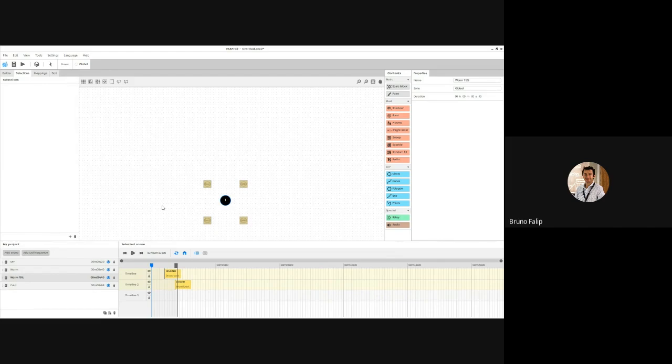Because, as you remember or not, when you trigger a scene, whether it's DALI or DMX, within a zone, it will automatically release the previous one. This is one scene at a time. And the problem with DALI is you only send your commands, so you may want to apply different scenes at the same time, which won't be possible if you merge with DMX.